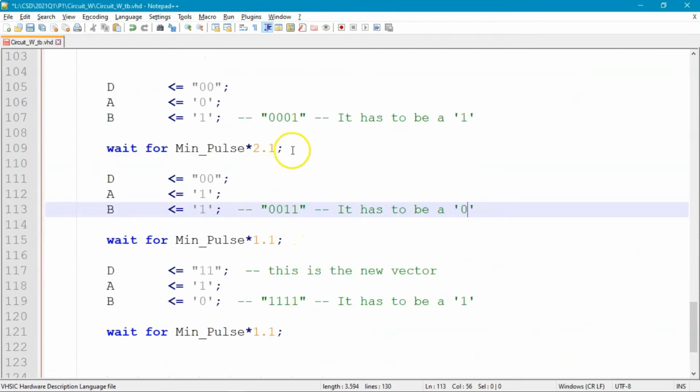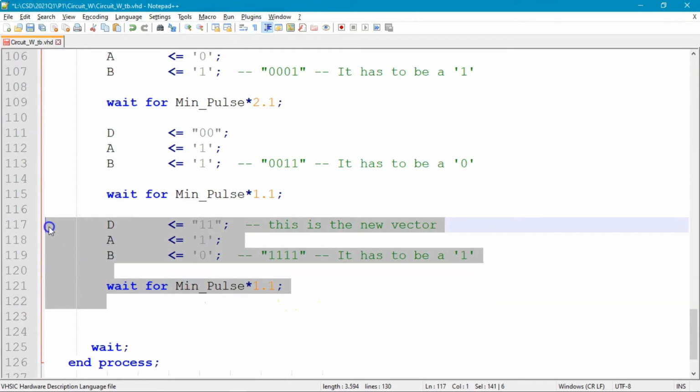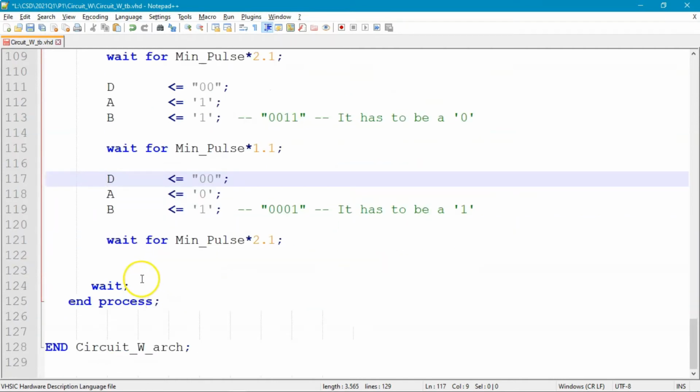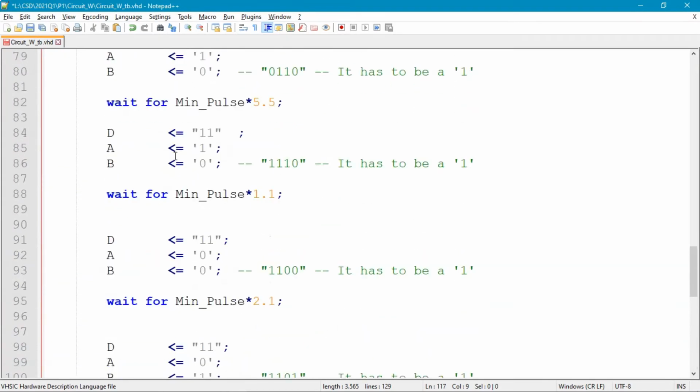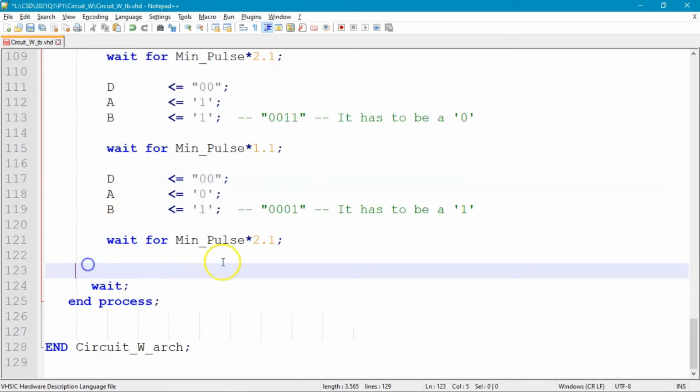So you did that before, so you can copy it, Control C down here, right? This way. And so on and so forth. So normally when this is going to work, after that you see that this is working, is your time to arrange the vectors that you are inputting here in a way that you are covering all the 16 combinations. But let's do that later. Now it's okay with these simple inputs. It's okay to check if everything is going to be all right. So you see the job of generating the test bench.